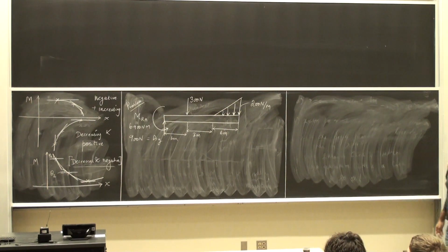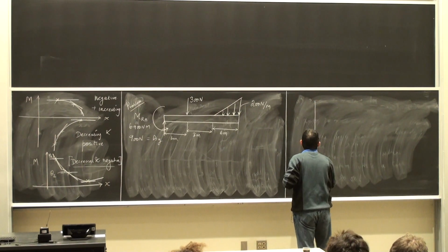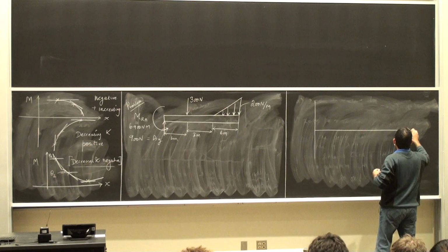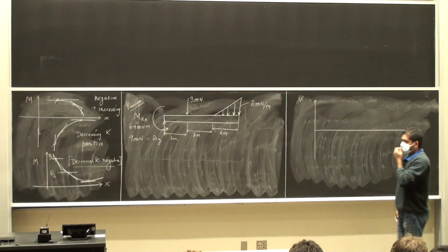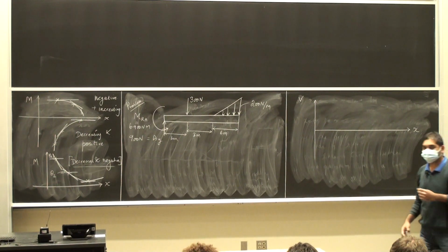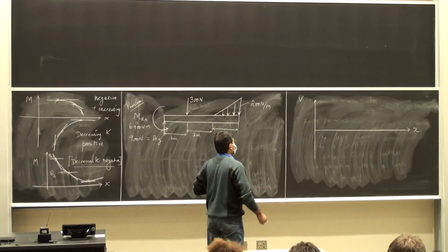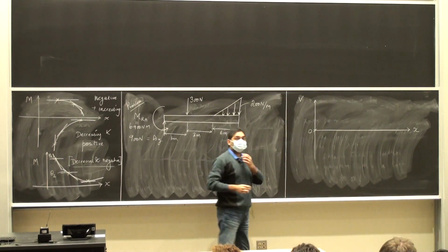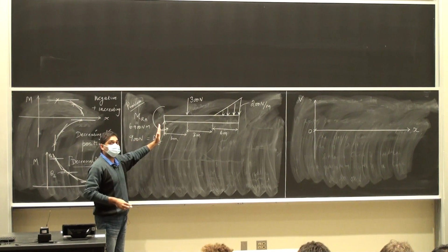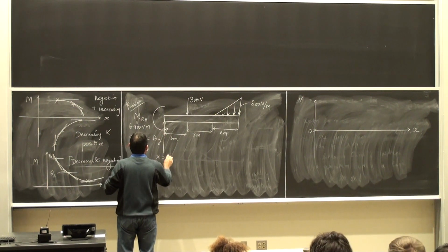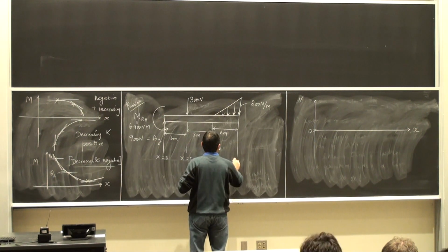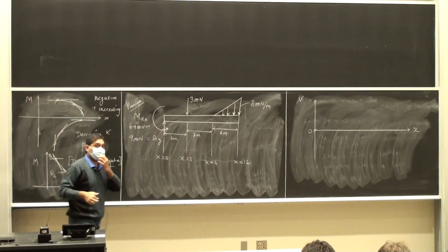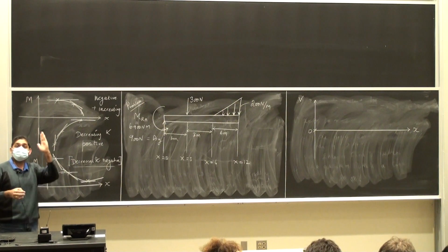Let's start off by drawing the shear force. Help me out. How do I start at x equal to 0? What do you see on the free body diagram? This is x equal to 0, x equal to 3, 6, x equal to 12. At x equal to 0, what do you see? You see that there is a force that is pushing you up, so you go up.